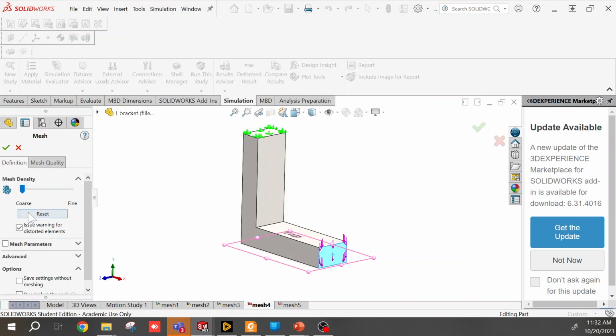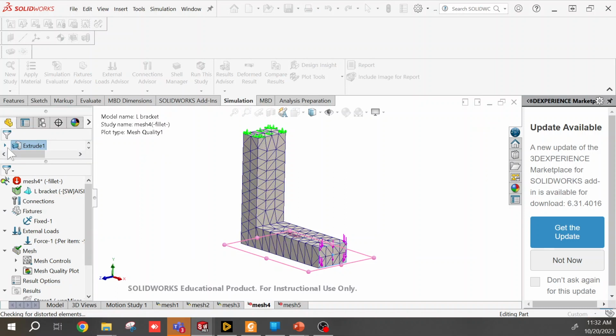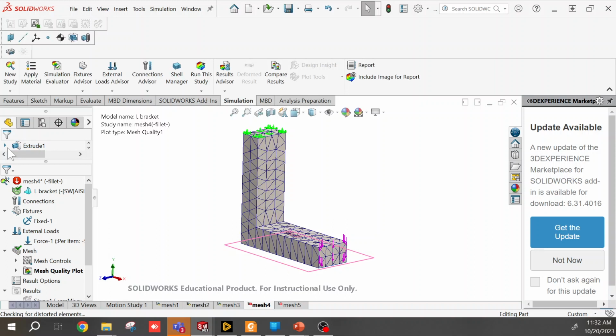And we're just going to slide it to coarse again because I want this to actually work right now. And you can see it gives us these nice coarse tetrahedrons, and there's pretty large elements at the edge of this particular shape here. Okay, so we'll click run because we have all the ingredients we need.